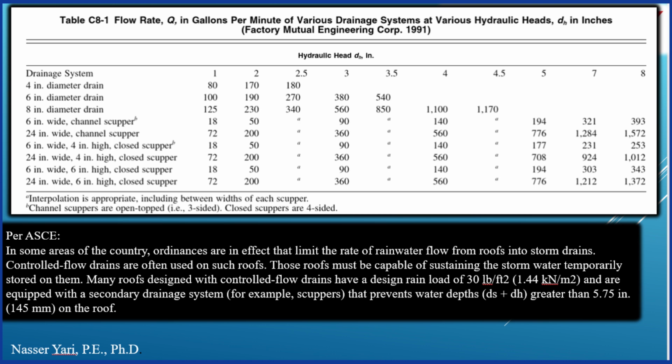I did a couple of jobs when I built a parking lot. We had storage for the water itself before we let it out to a drainage system, but here they have it on a roof. The same law applies, depending on where you are. So you've got to make sure you find out the local code and what they require. All right, let's go back to the problem.